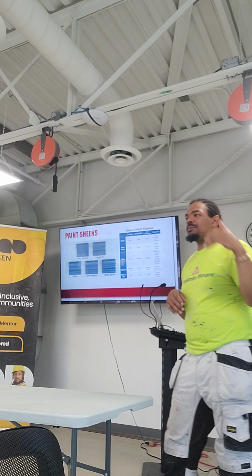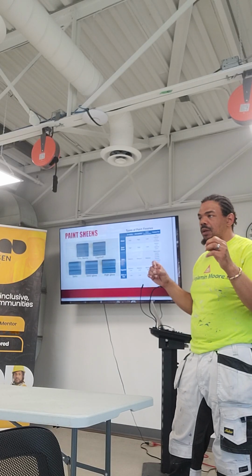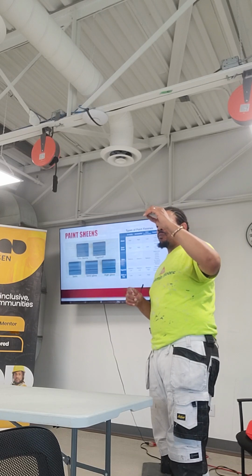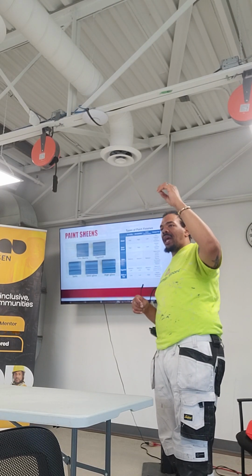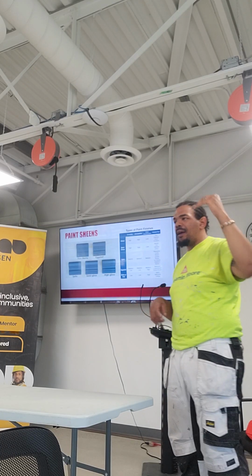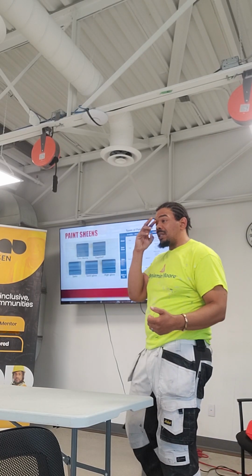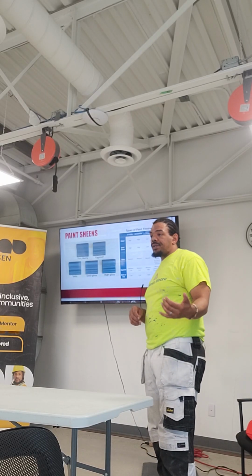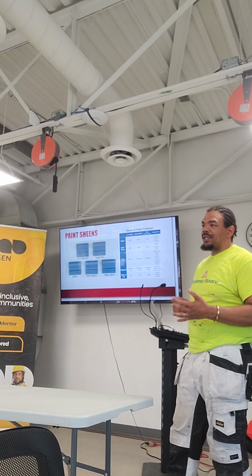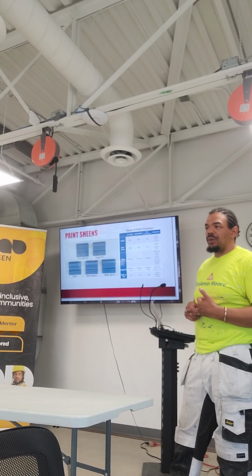Flat paint is used on ceilings because it has a lower sheen factor. There are some flat paints with zero sheen. So you stare at it at any angle and you don't see any light reflection coming off of it. You don't see any shimmer coming off of the paint. Light is not reflecting or bouncing off the paint surface at any given time. So that's a dead flat. Most ceiling paints are flat or dead flat. So that's an important thing to understand because then they have paints that you can use on walls that are flat. They have new technology in paint now where the paints that are flat now are washable and scrubbable. That's usually something that was reserved primarily for semi-gloss or gloss paints or eggshell even.